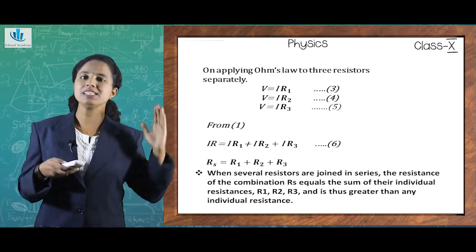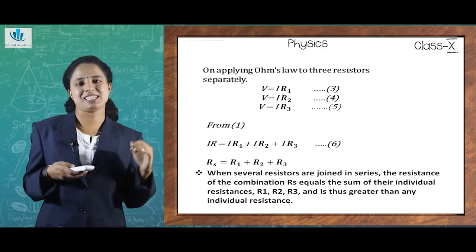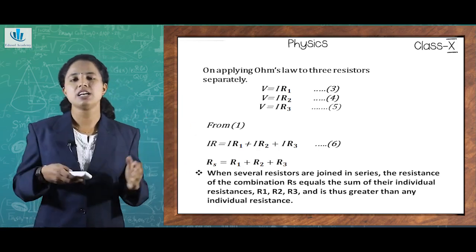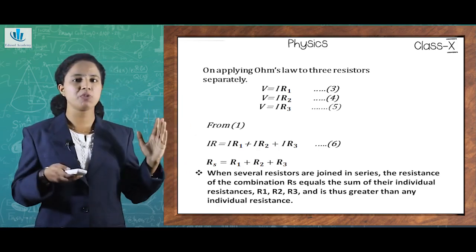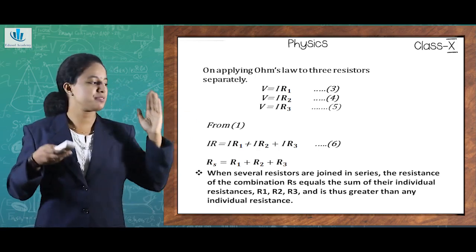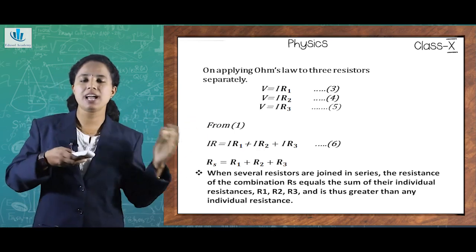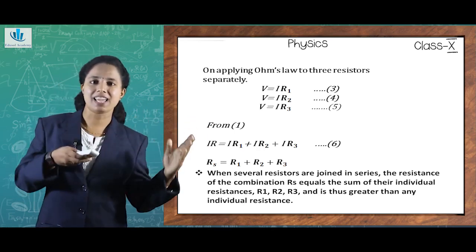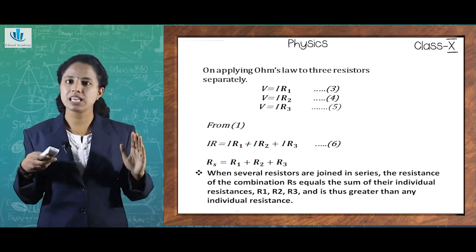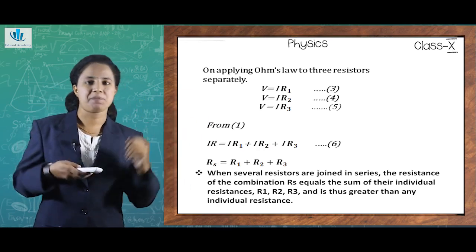So, potential difference is different for different resistors. So, we need to find it. I am first calculating V1, the potential difference across the first resistor R1. How can I do that? V equals IR, isn't it? So, V1 equals I R1.